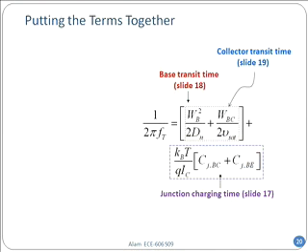Okay, so I'm done. You can see the junction capacitance part, right? Remember the junction capacitance part? In the denominator part, in the first part, this is the dQ_B divided by dI_C. Two pieces: how long it takes for the electrons to go through the base and how long it takes for the electron to go through this depletion region. Add them up, that's the whole thing.